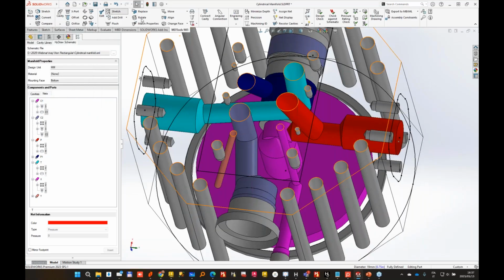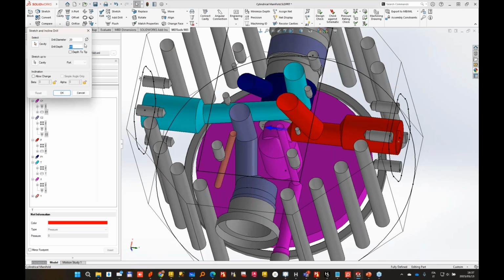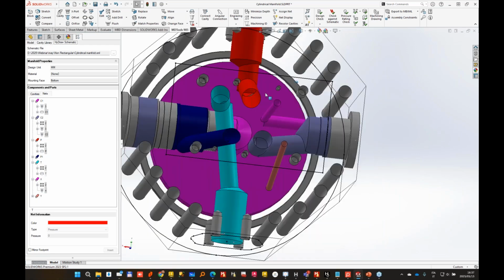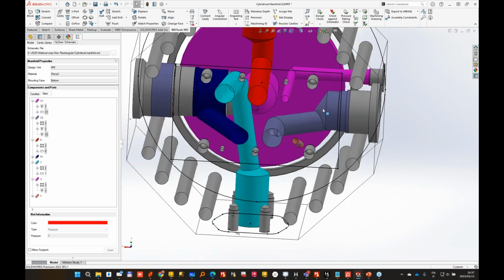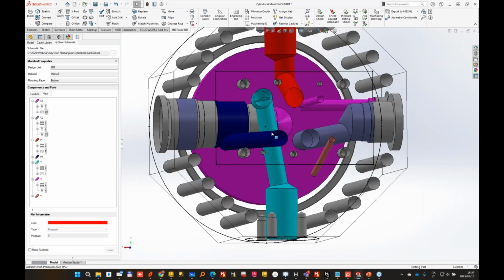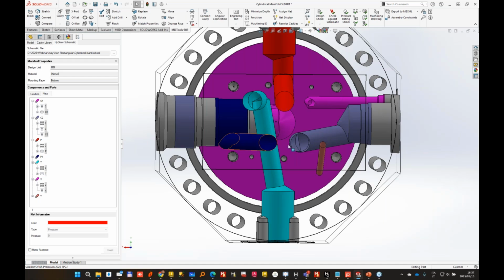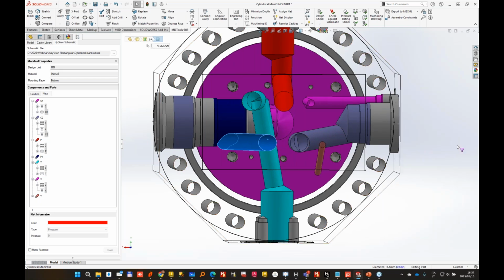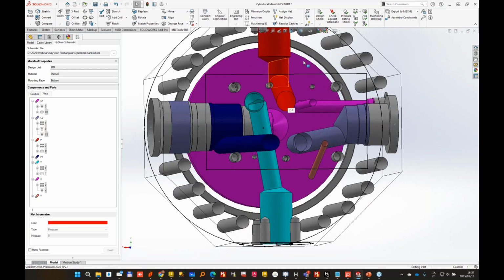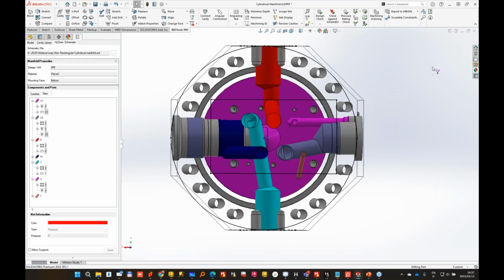knowing a bit of manifold manufacturing, this is a cylindrical manifold, so really it's a particular case. But when you are working one phase, unless you have 5-axis machines, you will not really be able to do in one operation incline drill with different direction. So if we take this direction, it's nice, we can do also incline drill very easily on the opposite direction, but if we do vertical, then with a 4-axis machine, this will require a different setting. So it cannot be done in the same operation.